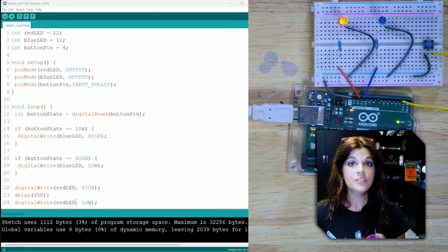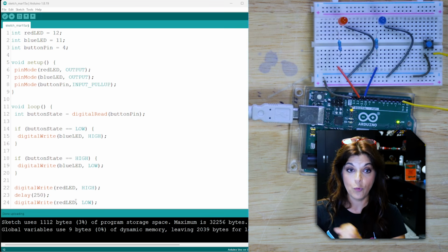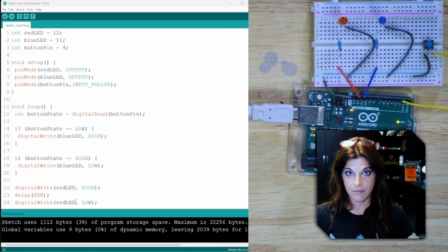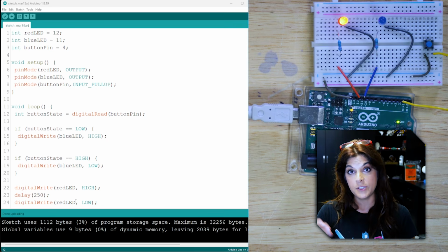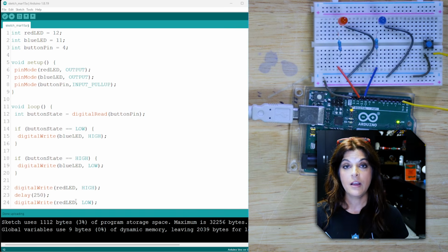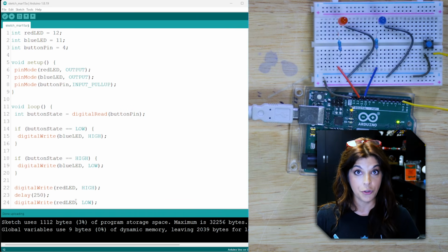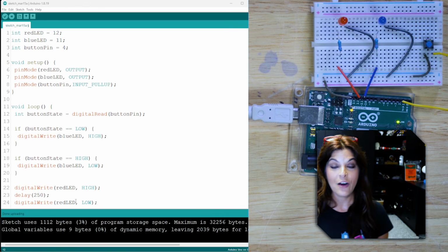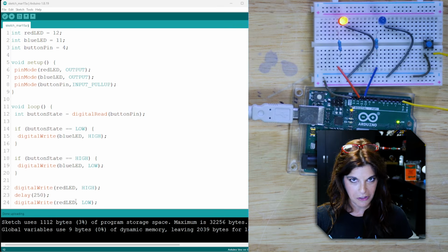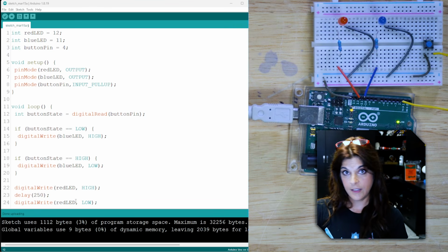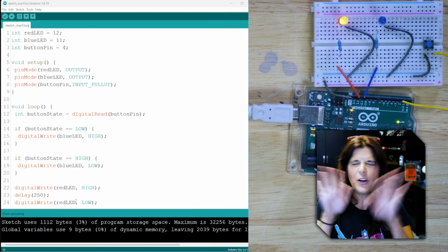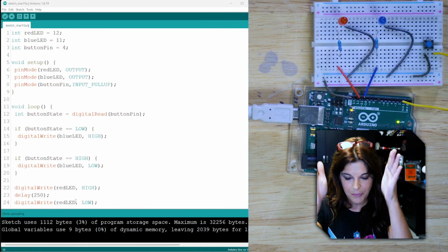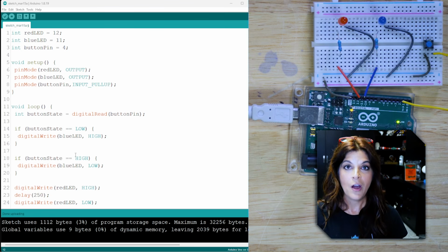All right, so how does one implement a hardware interrupt? Number 1, plug your interruptor into the correct pin, 2 or 3. You can also look at your board's data sheet and determine how many they have. Like the Arduino Uno has 2, other boards have more, so you might have more options in case you want many interrupters. Now you can have more than one interrupter, but they can only run one at a time. You can't have multiple interrupting. It becomes far too rude. Right now we're just casually rude, interrupting the Arduino from doing what it was doing. All right, so that's step 1.